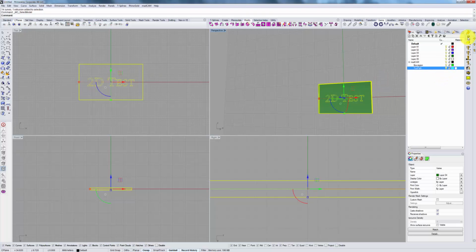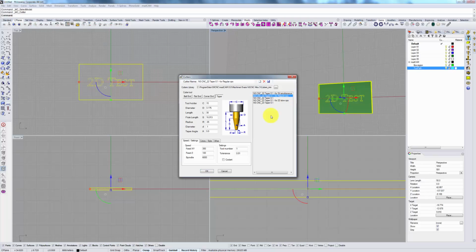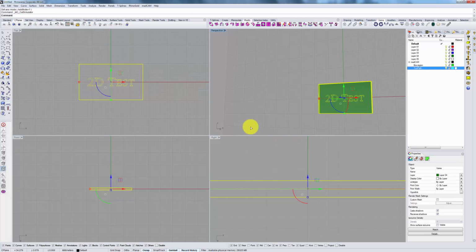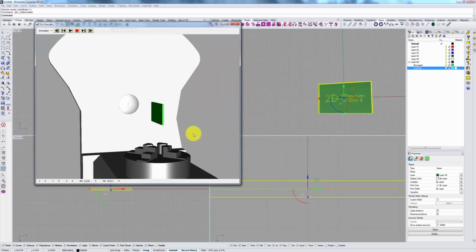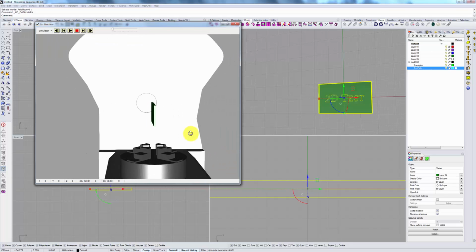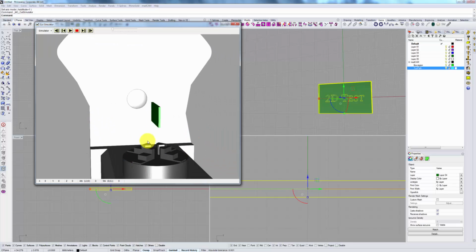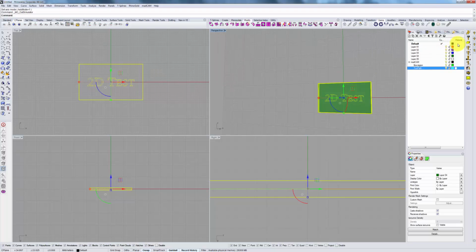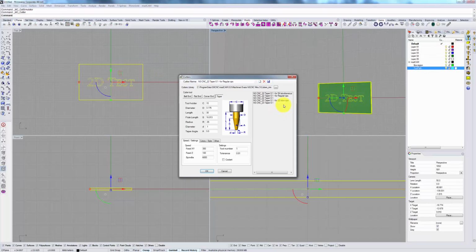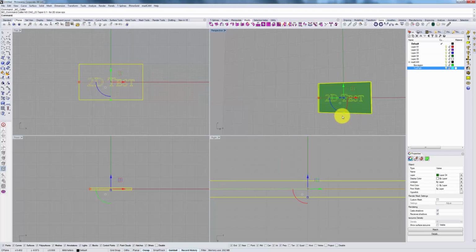To do that, as you might recall, you need to select the object, select cutter, and then click preview. As you can see, this orientation is good for a 5-axis mill because the arm can turn up a 90-degree angle and then this piece will lie flat. On the subject of tool cutters, by the way, for 2D operations I recommend creating a separate copy of a cutter with a slightly slower feed speed. This will assure that your two-dimensional cut will be nice and clean.